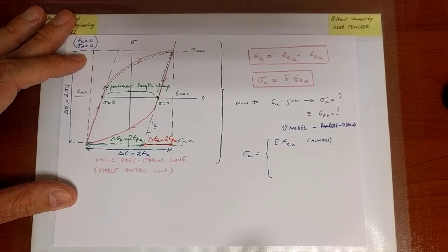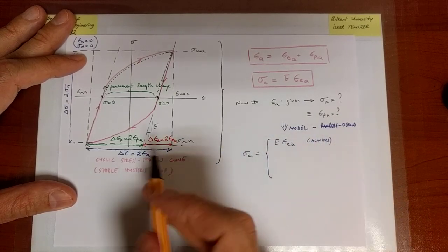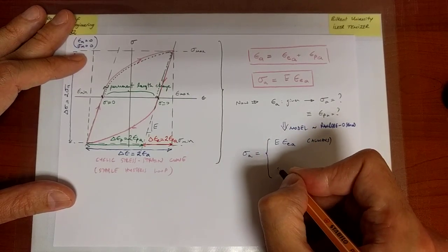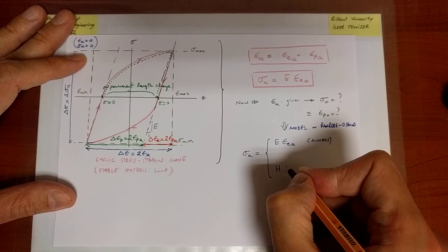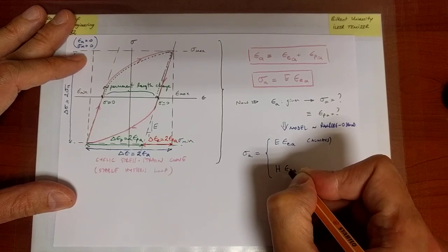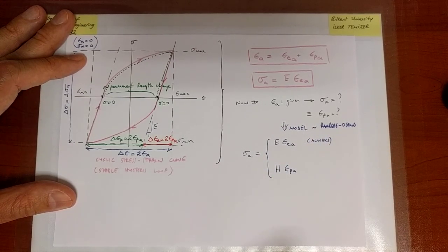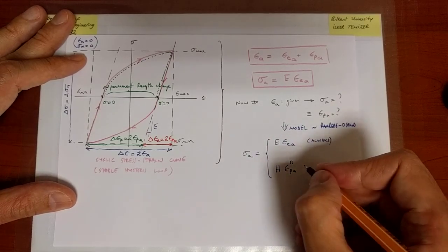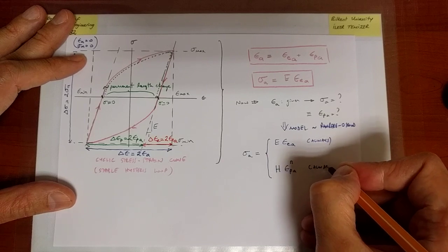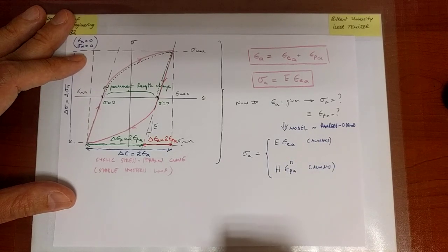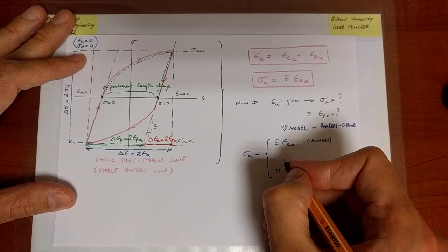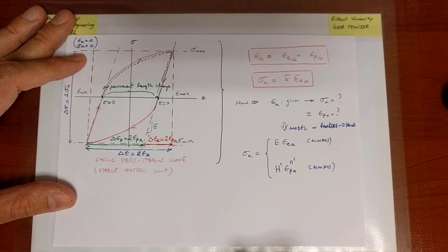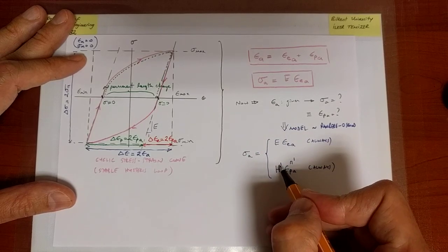And what's also always true in the Ramberg-Osgood model, again, we're using that because it fits this type of curve quite well, is that the stress can simultaneously predict the plastic strain, in this case, the alternating portion of the plastic strain, through a power relation. But we say that this is also always true. Now, we had earlier introduced the coefficients h and n, so to distinguish them from the uniaxial stress strain curve, we're going to put h prime and n prime.